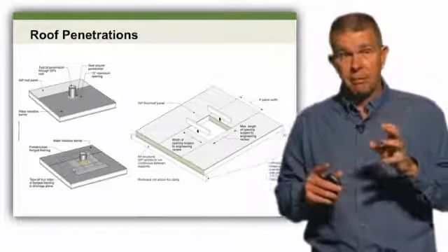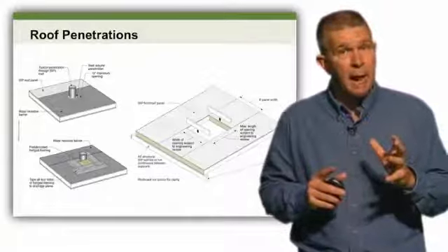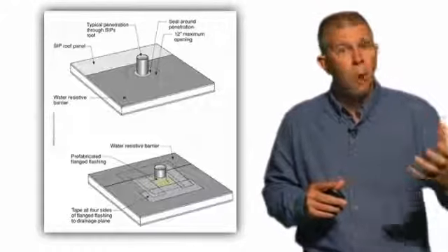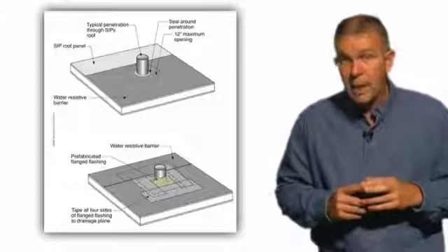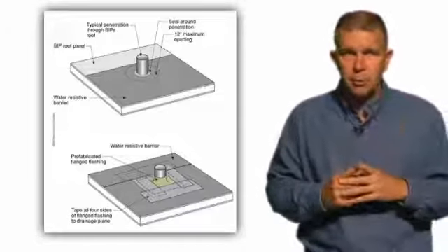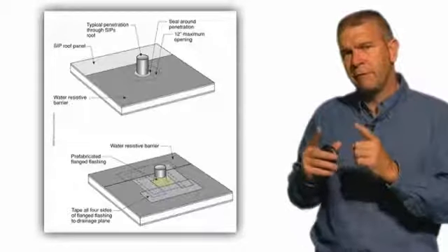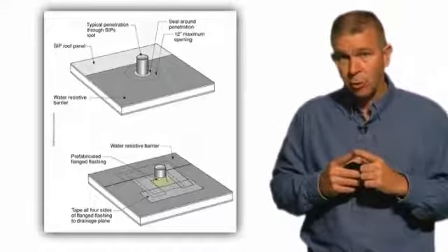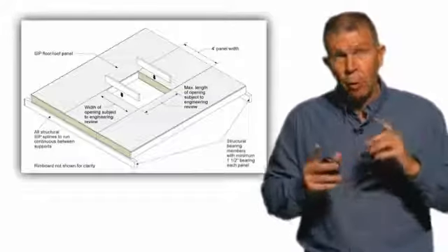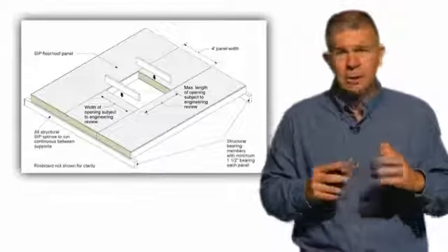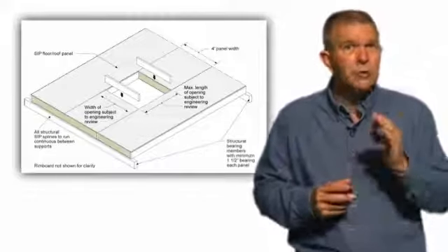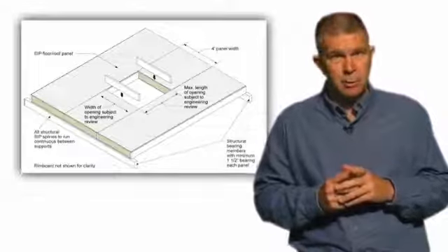From a design perspective, you need to control where these penetrations happen. If you're dealing with things like plumbers who want to put vents through the roof, let's think about how we can combine them to have the fewest possible, and where we're going to put them through the roof. One of the tidbits that I like to point out to builders is wherever you're going to have penetrations through your roof, just because in the future you may opt to add some type of a solar system or panel, it makes good sense to make your penetrations through your roof always on the north side of your structure. Leave that south side open. It makes future changes to the house and the acceptance of an add-on solar system so much easier when you're not having to go in and start moving things like plumbing vent stacks.